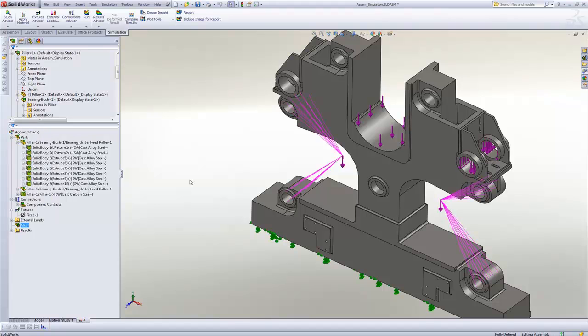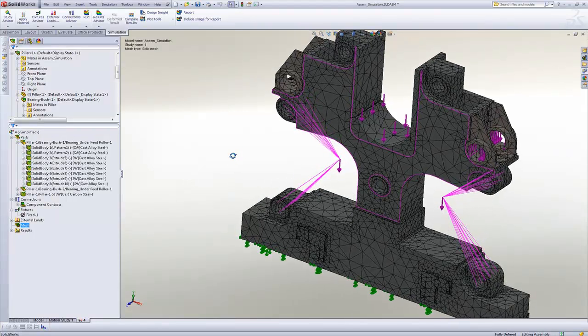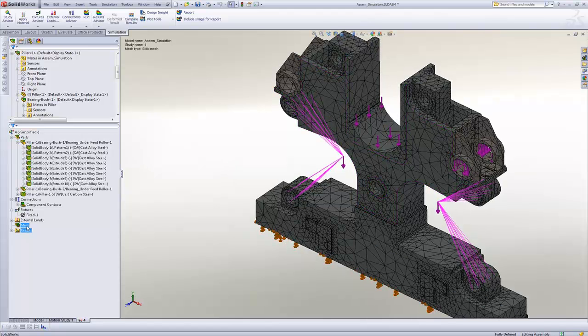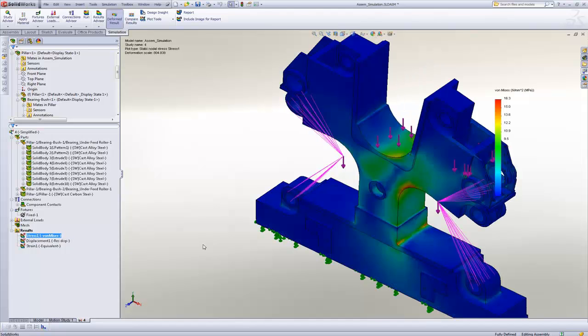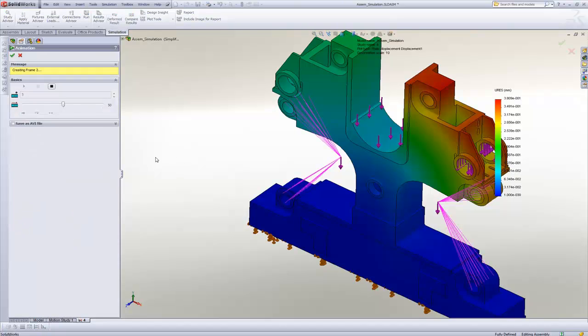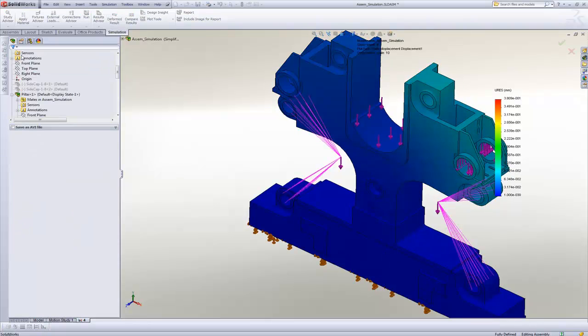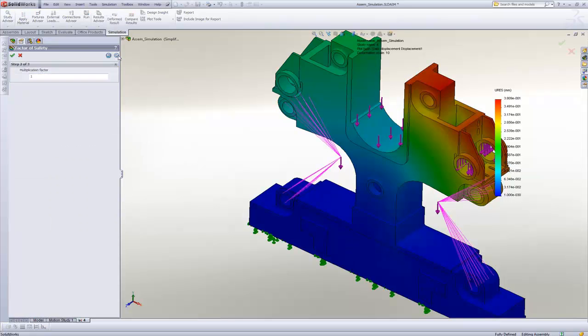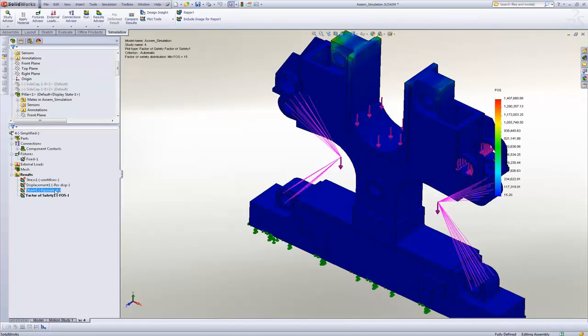Material applied in SolidWorks are automatically transferred to SolidWorks simulation. Contacts between parts in pillar subassembly are treated as bonded. To solve the problem, right-click on the study to run the analysis. SolidWorks will automatically mesh the model with default plots like stress and displacement generated. Let's have a look at the factor of safety plot. Minimum factor of safety is 15, hence design is safe. Further, one can use optimization study in SolidWorks simulation to reduce weight and cut down on material cost.